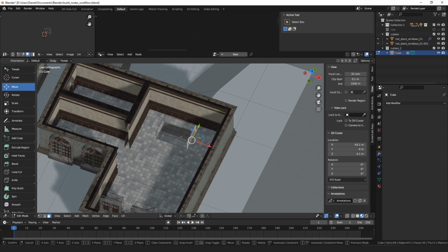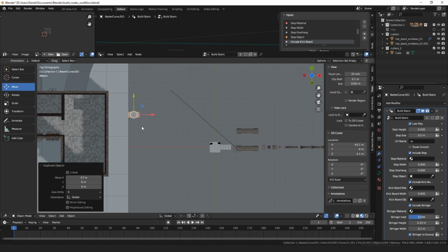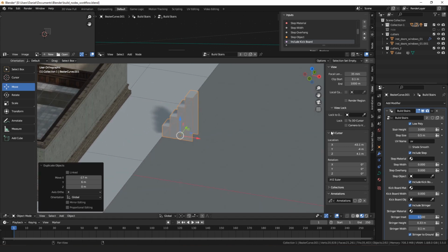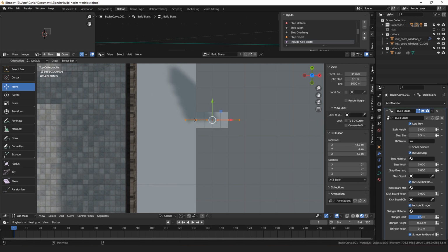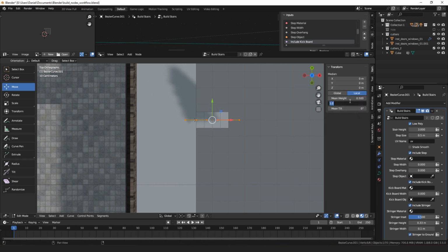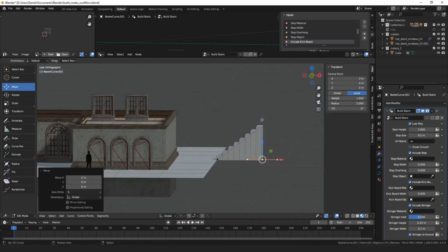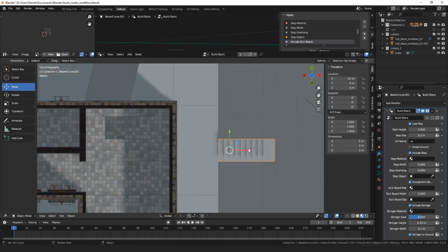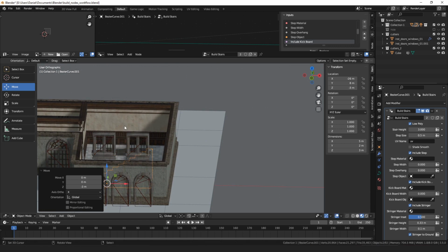So then we just have to decide where we want to put a staircase. So I have a stairs object here. If it's going from the basement up, we need that to be 3 meters tall. We want to set the radius on this to be maybe 2. And then we'll just adjust this till the steps look climbable. Drop this down.